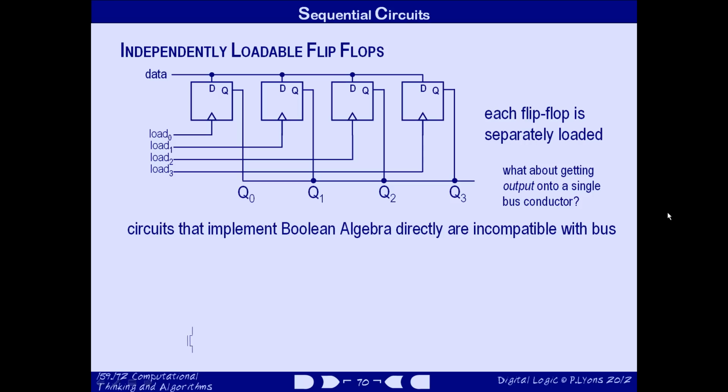Here's a schematic diagram of a transistor. It will conduct electricity from the top of the diagram to the bottom of the diagram, but only if that vertical bar on the left is connected to a high voltage. That's typically 5 volts or 12 volts, by the way, not the sort of high voltage that will give you an electrical shock. Now, if we connect the bottom of the transistor to a low voltage, ground in fact, 0 volts, and the top to a wire, then there's no connection between the point at 0 volts at the bottom of the transistor and the wire at the top,